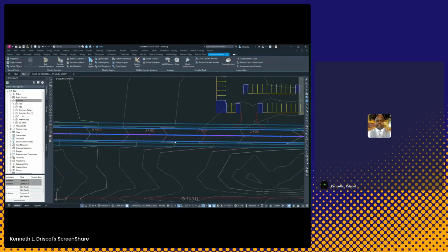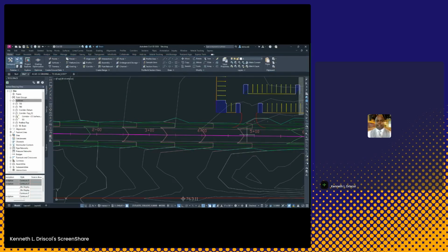I'm going to show you, if you right click and go to corridor surfaces, you can build a corridor surface. 2 and 10 design, I want to add the top because that's the finished grade. No overhang necessary, but the overhang from my curb going down to my edge of pavement, the bottom of my curb and gutter, then to my edge of pavement, I want the contour to follow that. And then if I wanted a boundary in here, I could shrink wrap it in terms of corridor extents. I'm just going to select OK, rebuild the corridor. And that's my corridor. And here's my grading.